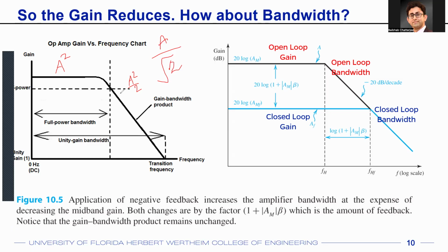All right. Now, what is meant here is that the full power bandwidth, or basically the bandwidth of the system, is, let's say, F, or F of op amp, or let's call it F for the time being. Now, what is important here is that the gain of the op amp is reducing in this direction. And if it is a first order op amp, as you increase your frequency by 10 times, the gain will reduce by 10 times.